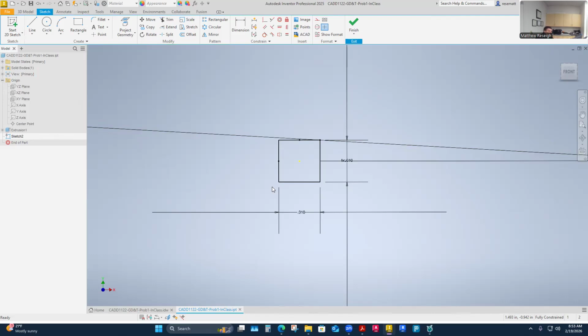So if I could make a circle with this, what I'm doing is picking the furthest point out on the rectangular tolerance, which would be the corner. All of these would be closer to this center point. But way out here on this very corner of this rectangular tolerance zone is about how far away I can get from my center. So if I snap a little circle here from the center to that corner, that's going to be a tolerance zone that is circular.